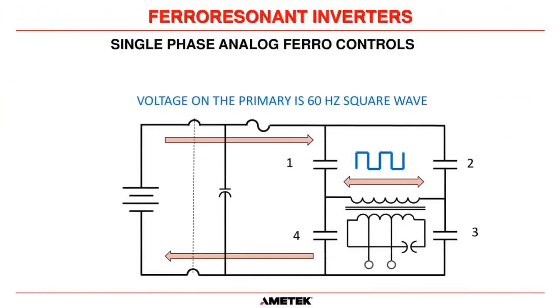So we start with an inverter bridge, or we'll start with DC over on the left here, and we go through a breaker and a capacitor bank. The capacitor bank there stabilizes the incoming DC. And then we're going to see later, it also absorbs kickbacks from the inverter bridge. We go through a fuse, and then I'm showing contacts right now for switches. Later, we're going to see those become SCRs right there.